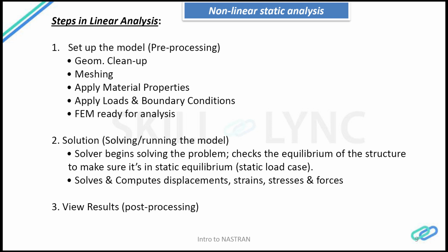And then once you submit the job to the solver, what happens in linear static analysis is that, at the very beginning, the solver will check the equilibrium of the structure, whether it is in static equilibrium.